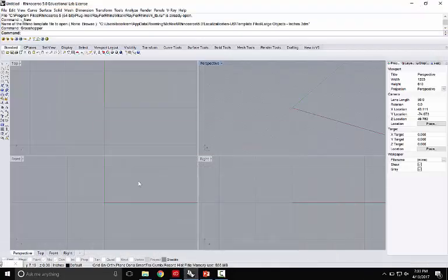So working in Grasshopper this way, we're actually going to talk about how to write the script so that you're not deriving the shape from a given form, but instead allowing the form to be driven by the unit of the brick itself. So what we're going to start with is the brick size, and then develop the geometry, the constraints of the geometry, based on that brick component.